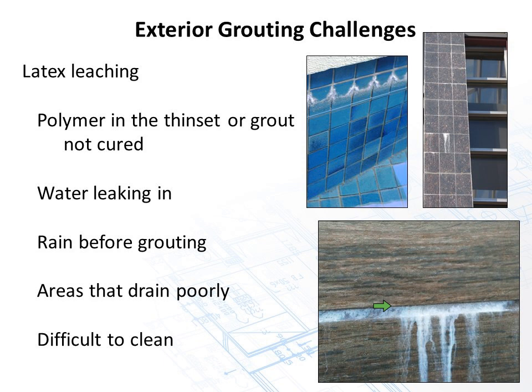It is not fun. It's not fun to clean up. It's just like trying to clean up a diluted paint, if you might. But we see this a little bit more today with cement board installations than we did years ago when we put a mortar bed up. So in this case, if this was a mortar bed, it would have been sand and cement over a building paper for that matter, metal lath, 3/4 of an inch.